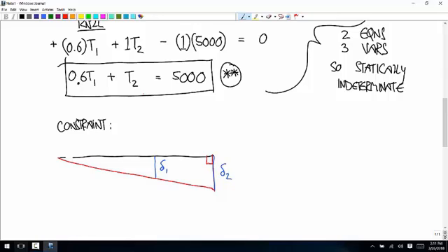Now, if you really did a finite rotation of this bar, this would not be a right angle, because if it's rigid, this has the same length as this, right? And so this would be an isosceles triangle. This angle would be the same as this. But we're talking about vanishingly small changes in angle. That's part of our expectation that deformations are small. And so we can approximate this as a right triangle, and it's going to make the math a lot easier.